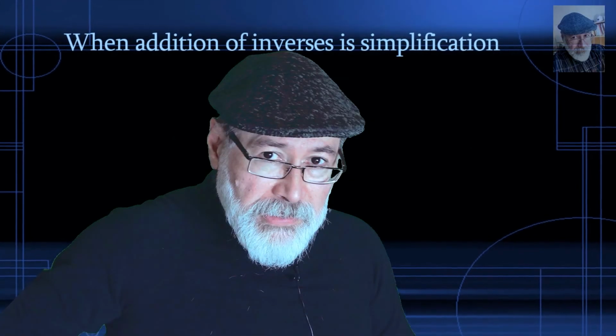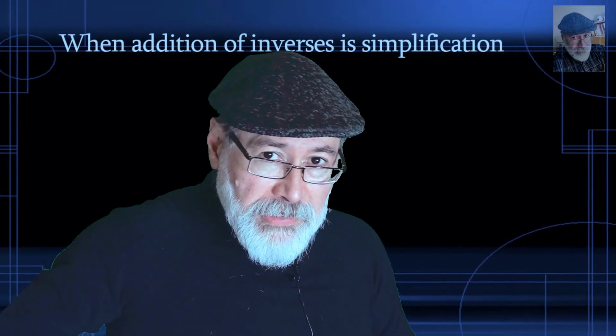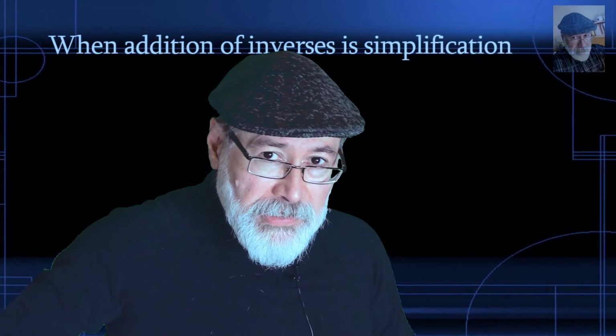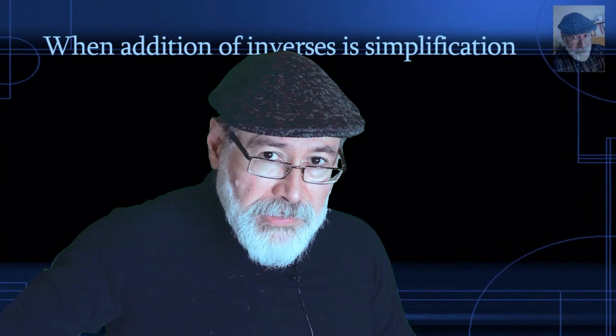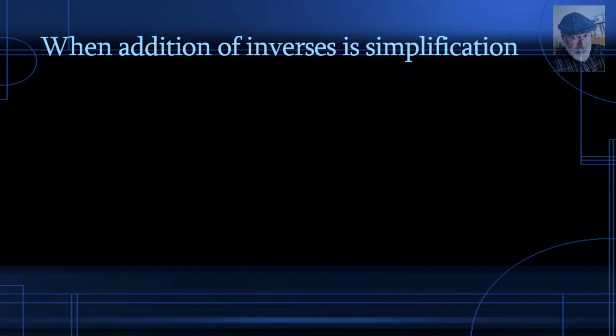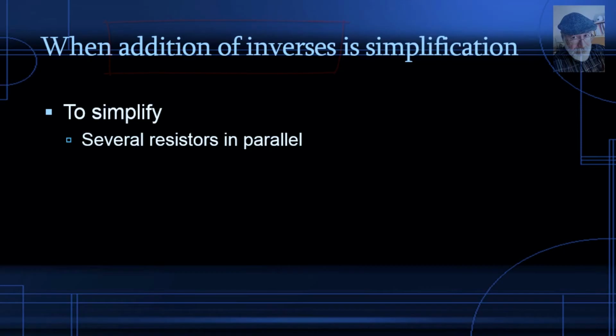The same way as I showed you a moment ago, that there are many times in which we achieve an equivalent just by adding together the parameters of the elements that we are combining, I will show you now that there is another group of cases in which we achieve equivalence by addition, not of the parameters, but of the inverses of the parameters. Let's see. To simplify several resistors in parallel, we add their inverses. To simplify several inductors in parallel, we add their inverses.